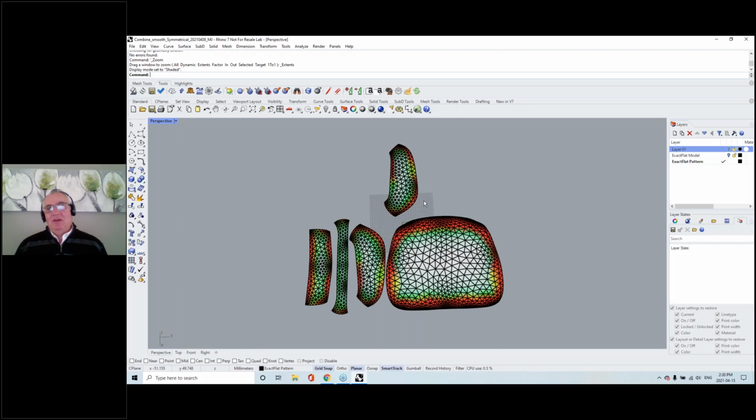So I'm going to select the material that the headrest is made out of and flatten based on that material type. And that's one of the things that makes this flattener so unique and so accurate, is that you actually can address the material properties. So if this was a leather headrest, it's going to flatten the material as if it was leather. If it was a nylon, I'd flatten it based on how nylon flattens.